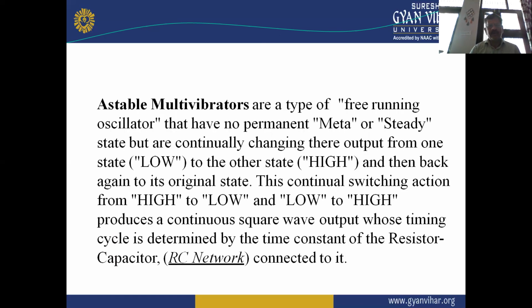Astable multivibrators are a type of free running oscillator that have no permanent or steady state, but are continually changing their output from one state, low, to the other state, high, and then back again to its original state.